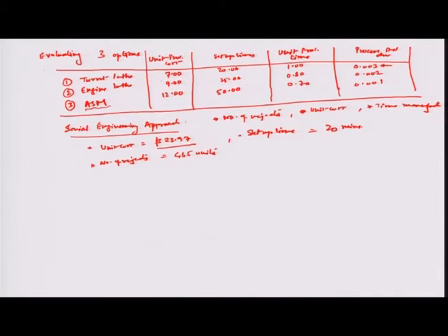These were the numbers produced which were defective. So, for every 1000 pieces of production in the transformation system, you have to enter exactly 1465 pieces, out of which 1000 good pieces will emerge, and 465 would be the scrap which would get produced. So the inputs were 1465, outputs 1000, scrap units 465. So, number of rejects in this case was 465 units for the turret lathe.